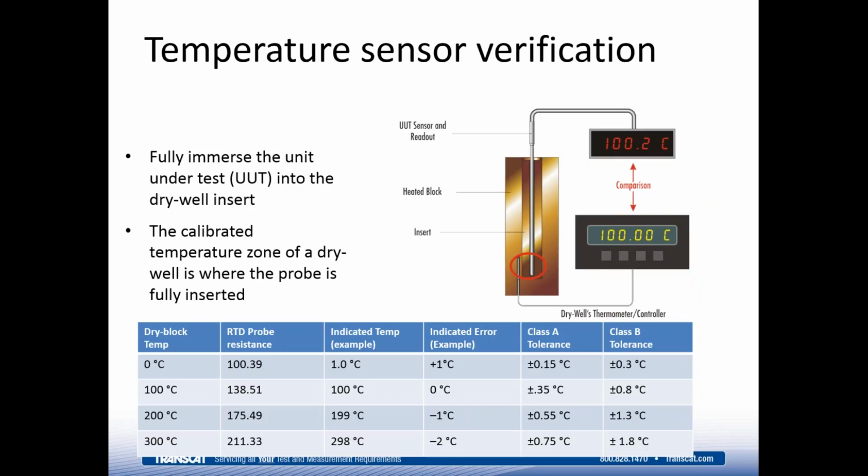It's going to start to what we call anneal, which removes some of the stress from the probe. And so you're trying to collect as-found data. You'd like to know what this probe was like at the beginning, before I even started to calibrate. And to do that, you really want to start at the lower temperature.